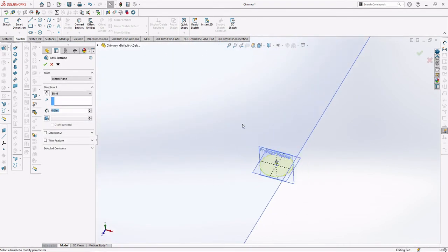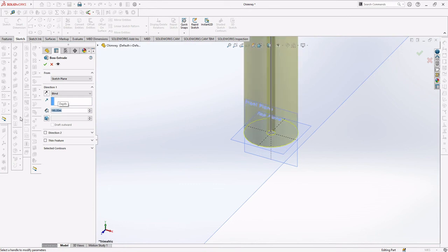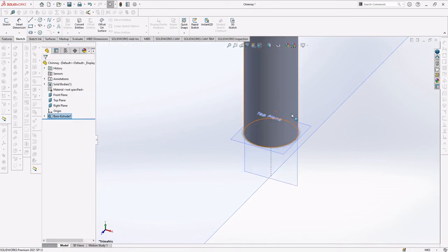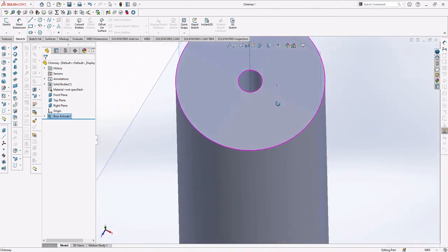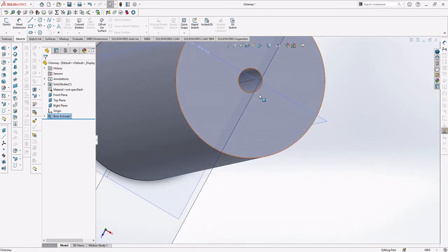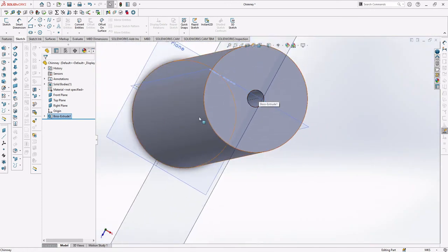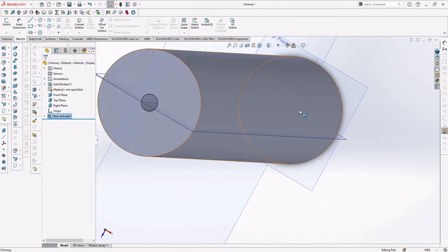Now we can extrude this for 190 meters. So this gives us a cone that is hollow inside. Now we need to create actually another extrusion of cylinders, and that cylinder will be needed to create a boundary for the zone that is not rotating.